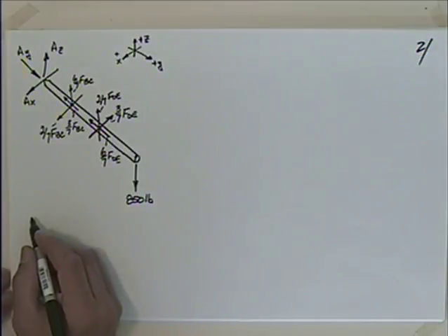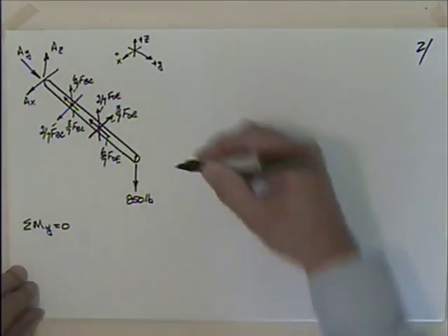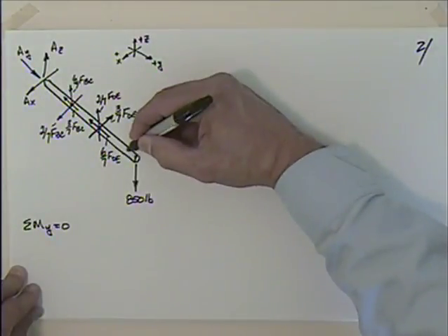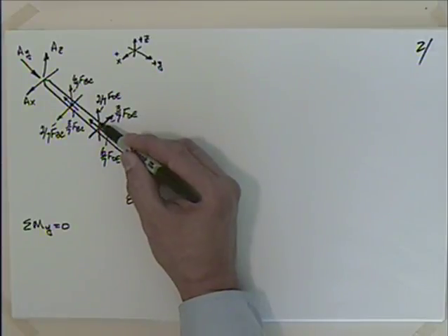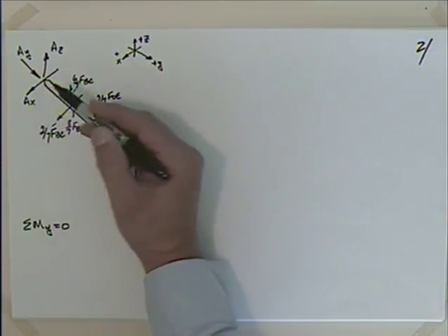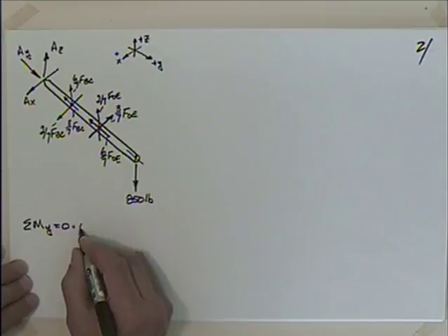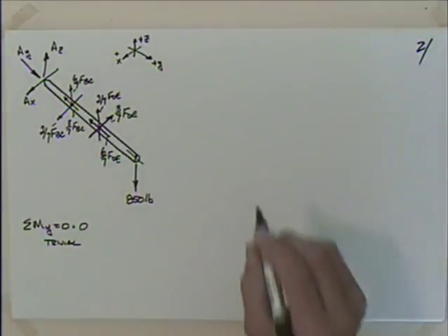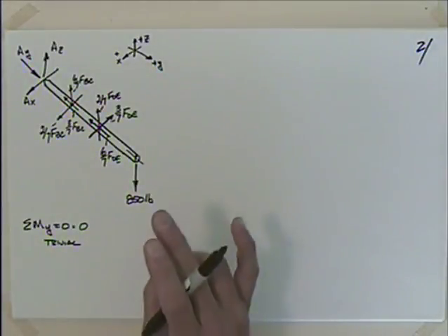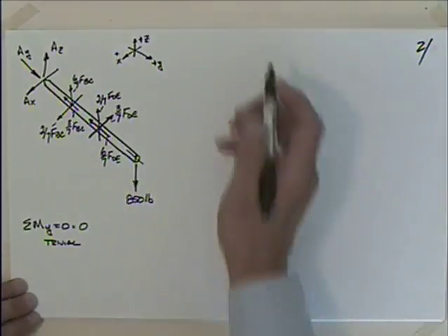I could sum the moments about the y-axis, setting that equal to 0. What do we have about the y-axis? Remember, this is the y-axis, straight out there. Everything intersects the y-axis, so there is no distance. Force times distance, the distance is 0. That's trivial. Okay, so hopefully we don't have any more trivial equations, because I now am left with possibly 5 equations and certainly 5 unknowns. Well, let's continue on then.